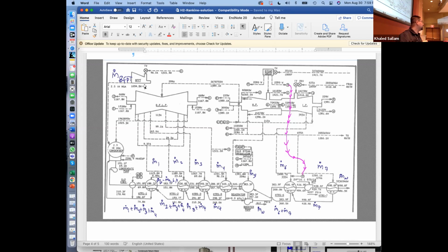It has its own turbine. So when you go to the power plant and you see the big high pressure turbine and the intermediate pressure turbine and the low pressure turbine, you see a smaller one on a different shaft next to them: the BFPT, the boiler feed pump turbine. So a turbine coupled with the pump, because they realize that I cannot make electricity and then use the electricity to turn an electric motor